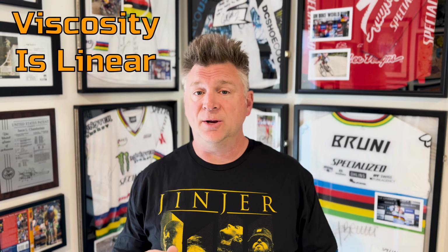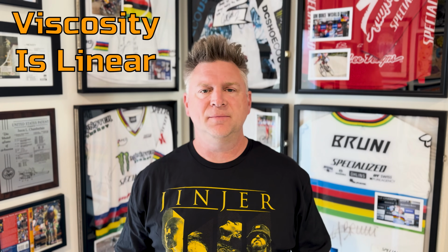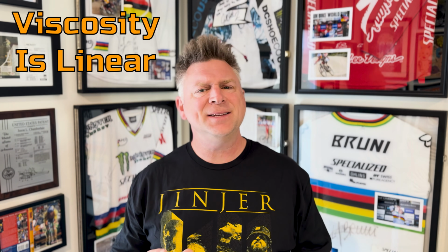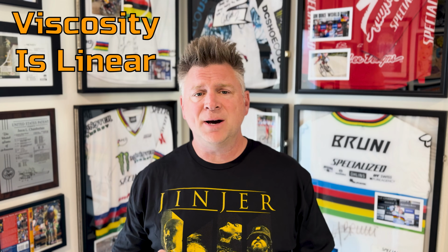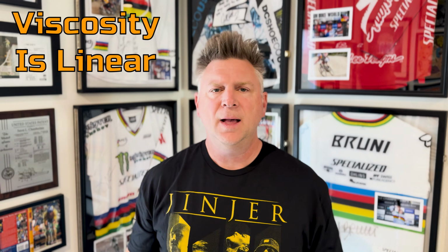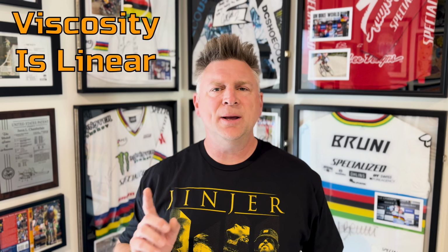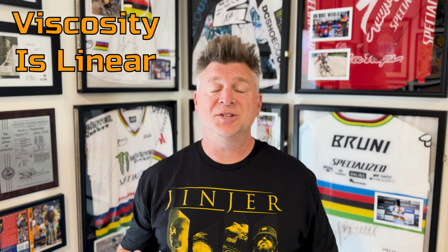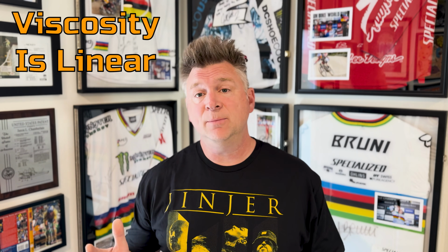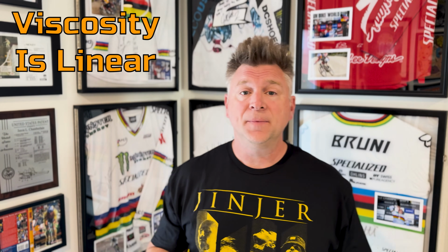So what does this mean for us trying to tune a vehicle? We've established that oil weights are linear within a manufacturing tolerance. We've also established that the labeling is not consistent. The numbers on the bottle are not always exact. I recommend that you consider the number on the bottle to be nominal, just a name. They might as well be labeled A, B, C, D, E, F, U. Consider the numbers to be relative to each other and not absolute numbers.